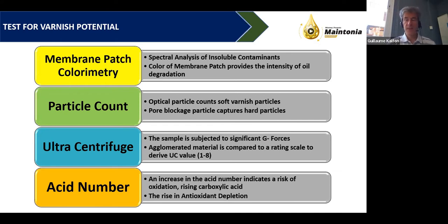But also, sometimes it gets sampled, sent to the laboratory, analysis is performed, but lo and behold, and that's a pity, it's even a bit sad, tests that are absolutely needed are not done. So there is a whole operation of sampling, sending, analyzing, writing and printing the report, and getting the report back to the machine and reading and trying to understand how the machine is doing. But this whole activity is largely wasted. Why? Because we haven't done tests that the machine really needs.